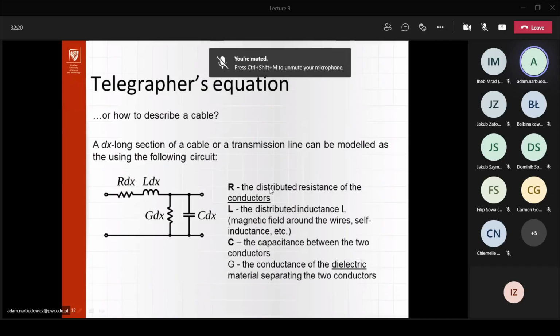However, all of them will be included in the impedance, but not all of them are responsible for the losses, at least losses in the sense of ohmic losses, so attenuation. So if you think about the inductor, again we're talking about the perfect inductor here, in the case of an inductor there are no losses involved, really.